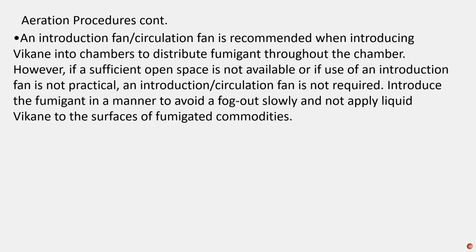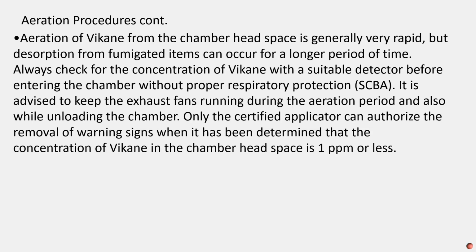Aeration procedures continued. An introduction fan, circulation fan, is recommended when introducing Vikane into chambers to distribute fumigant throughout the chamber. However, if sufficient open space is not available, or if use of an introduction fan is not practical, an introduction circulation fan is not required. Introduce the fumigant slowly, in a manner to avoid a fog out, and do not apply liquid Vikane to the surfaces of fumigated commodities.